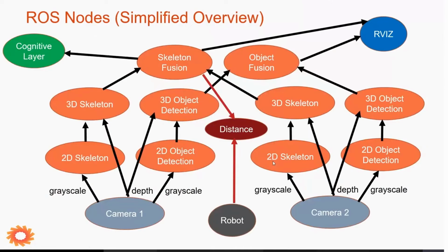Okay, now this is about how this is actually implemented. So in Rossini, we use the ROS operating system, the robot operating system, which allows you to have lots of different software nodes, which are independent software computer programs which read information from the pool of topics and then process them and create their own ROS topics, which is again a data stream which can be subscribed to by subsequent programs for further processing.